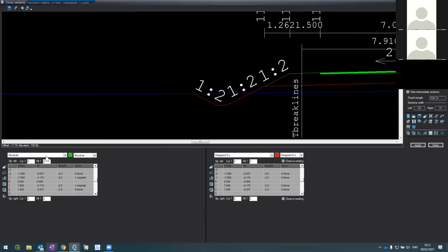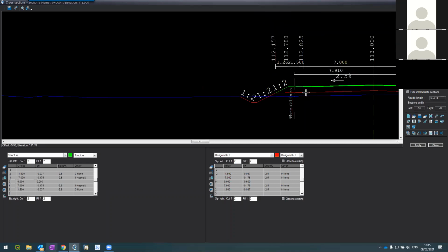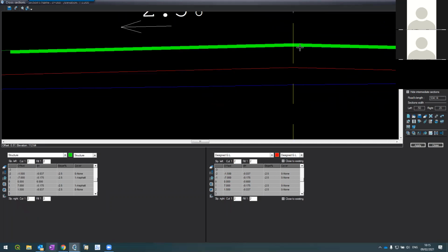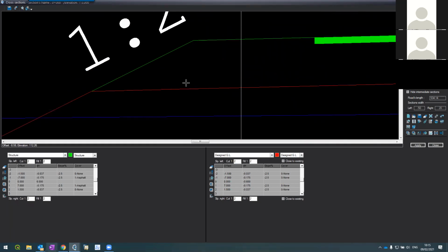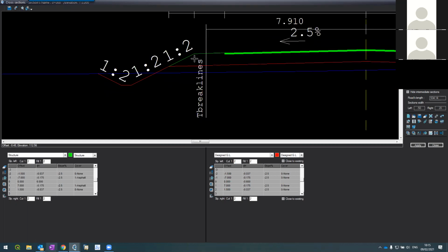And then from here, first of all, we designed the structure total width. How did we do it? We did it by defining the design ground level, the subgrade level. We went from here 60 cm down, so here it is 0 minus 0.6. And from here, we continue until this point, meaning 7 meters and 1.5 meters. From here, the software knew how to complete by itself.